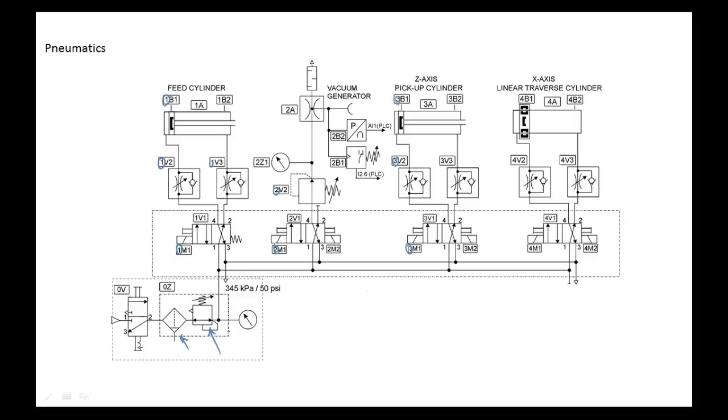So one of the tricks they did, and one of the things when you go through troubleshooting, one of your first things is to pull a visual inspection, right? And then the next thing to do is to verify power. And of course, on these we have a fluid power and we have electric power. If either one of those powers are not working, then the section's not going to work.